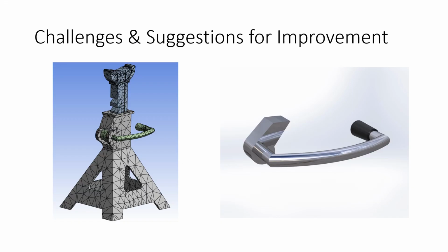Finding a perfect way to accomplish the mesh convergence study was not easy in Ansys. The program uses an algorithm in which it selectively defines mesh element sizes based on the part of the geometry. Since the only way we found to resize the mesh was defining element sizes as a constant throughout, we were unable to replicate the default mesh using varying element densities. A suggestion for improvement would be to render a more accurate geometry for the internal portion of the adjustment arm. It was inaccessible without damaging the shear pin in the jackstand, which would render it useless without repair.